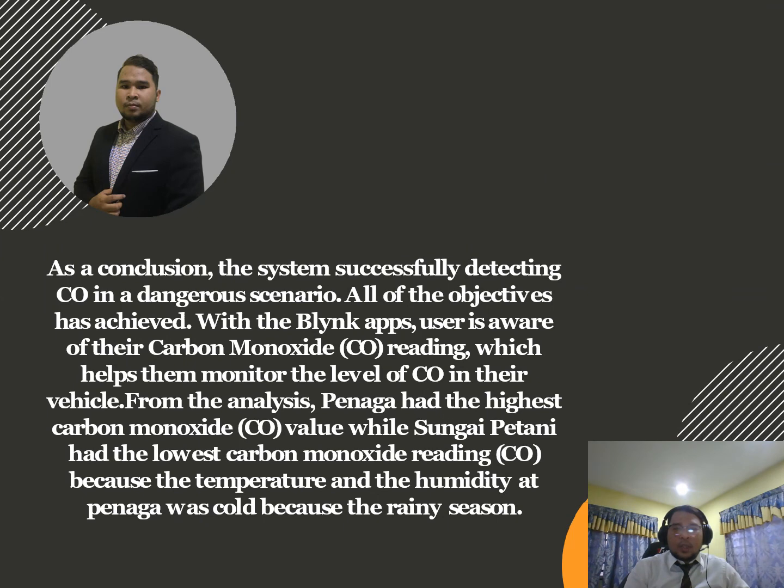As a conclusion, this system successfully detects CO in a dangerous scenario. All the IoT objectives have been achieved. With the Blynk app, the user is aware of the carbon monoxide reading, which helps them monitor the level of CO in their vehicle. Aside from that, users also get notified or alerted if CO exceeds 1800 ppm, where the system will activate the warning or alarm system.